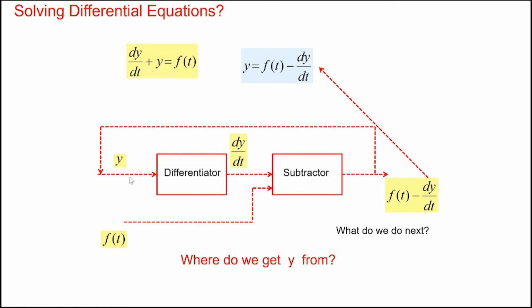So now if we set it up and leave it, the output y, or the signal that you get here, would be the solution of this particular differential equation given any particular excitation that is given over here. All right, so using this we can solve second order differential equations also. Now normally integrators are preferred over differentiators, because in differentiation any small non-ideality, any noise will get differentiated and will have a significant effect on the circuit.